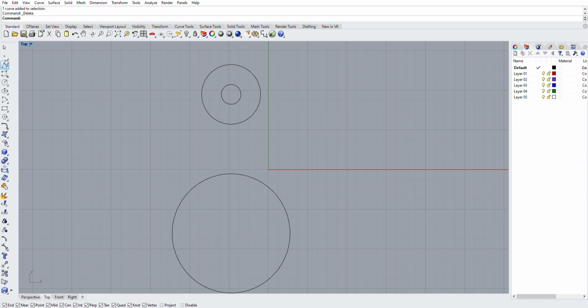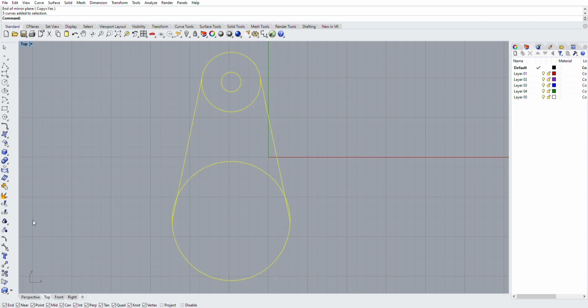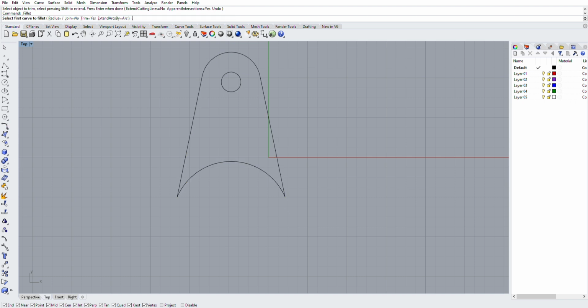And we're going to go over and pick our line tool. From the line tool, we're going to take from the left edge up to the tangent. We use tangent because that's the one that flows properly over the circle. It's just one complete line. We're going to use the mirror tool, select everything, back to the trim again, and cut off all of the stuff on the bottom here, cut off the intersecting lines that we don't need, cut out the radius from around the bushing, and go grab the fillet tool.